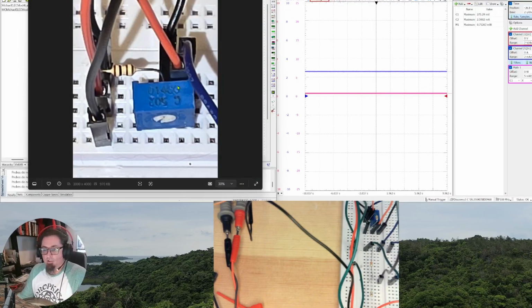Finishing our circuit, we're going to take potentiometer C502 and a 100 ohm resistor, which is right here. We're going to hook up the A portion of our bridge circuit right here, and then I'm putting the first channel right here off of the first plug pin to the potentiometer.